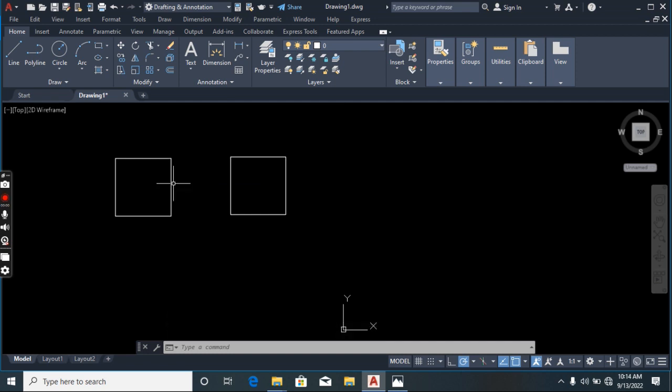So now the difference between this is this. Let me click this that I used line. You see, it's just one side that is clicking. Let me click this. You see all the sides. So at the end of your drawing, maybe you want to draw a machine part, and you have drawn and you want to join all the parts. You see there's stress in joining. So when you use polyline, there's no need of joining. Everything has been joined already for you.